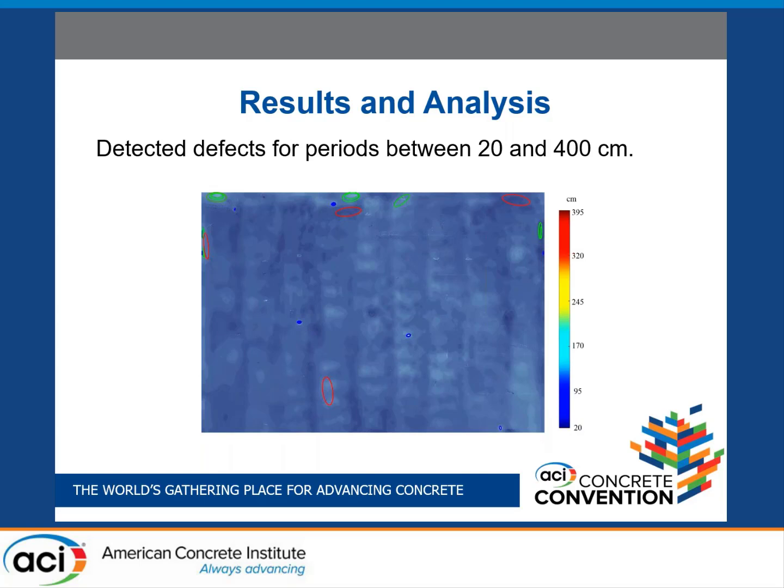This can support the analysis of waviness with essentially any characteristic period, in other words, wavelength. So this enables the approach to study waviness not just for a few distinct wavelengths like 2, 4, 6 feet, but for dense and large ranges of wavelengths. This figure demonstrates that these ellipses show possible areas of defects for these periods.